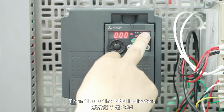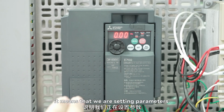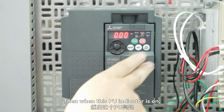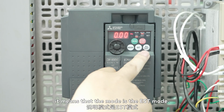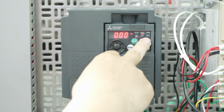Then this is the PRM indicator. When the PRM indicator is on, it means that we are setting parameters. Then when this PU indicator is on, it means that the current operation mode is the PU mode. When the EST indicator is on, it means that the mode is the EST mode. Then the NET is the network operation mode.